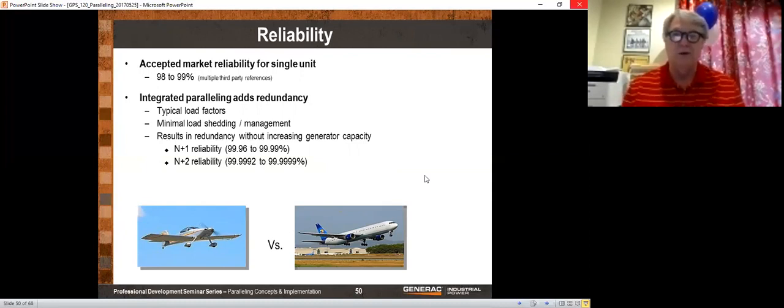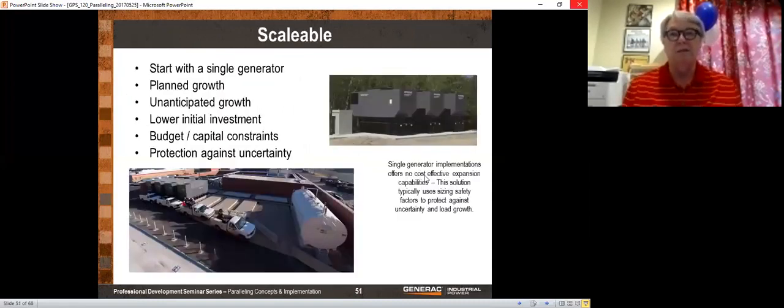So we actually have N+2 redundancy. And what's not to like about that? There are just so many advantages that you would not have gotten with the 2 megawatt generator. And this is fairly typical. People buy an MPS system, which stands for modular power system, in order to get reliability and so on. They end up with redundancy, even though they didn't buy it.